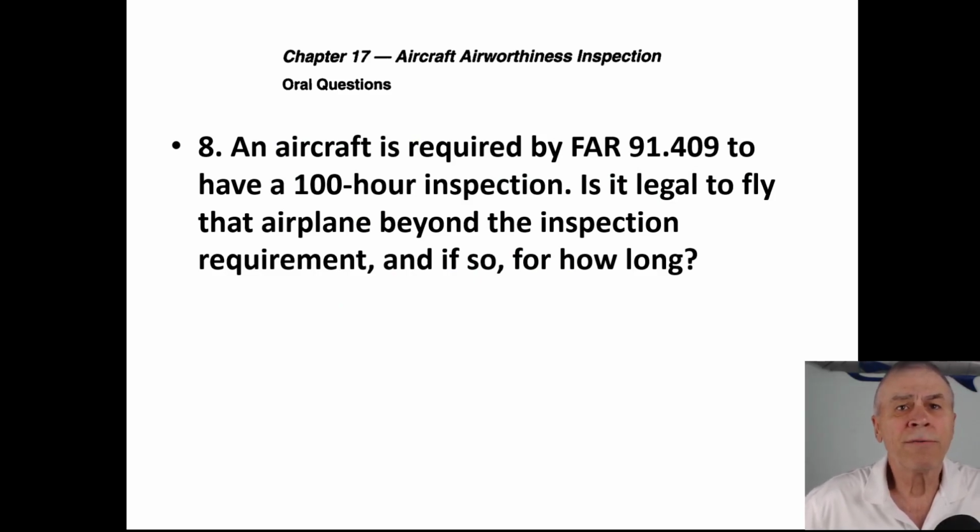Oral question. Aircraft is required by FAR 91.409 to have a 100-hour inspection. Is that where the requirement was? Yes, it was. All right. I do get my 91s and my 43s mixed up. 43.11 was the entry. Yes, 91.409, which was just labeled inspections, is the requirements for the 100-hour inspections.